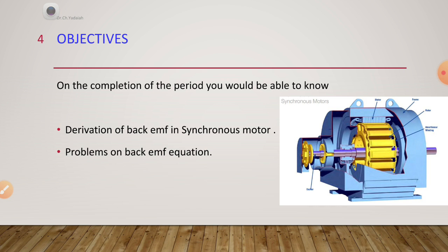The motor works similar to a three-phase induction motor. Once the rotor reaches nearly synchronous speed, then the DC supply is excited to the rotor.